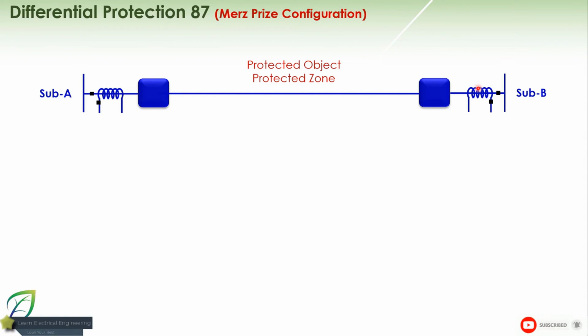So here, what does the term protection zone mean? It means the transformer plus the cables extended to the high voltage and medium voltage side, plus the circuit breakers and the section of the bus bar located inside either the switchgear or inside the GIS. Very nice. Okay, let's go back again, what do we have? We will talk in general terms, and then we will reflect this discussion in the upcoming lectures.